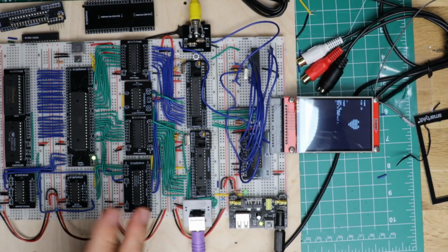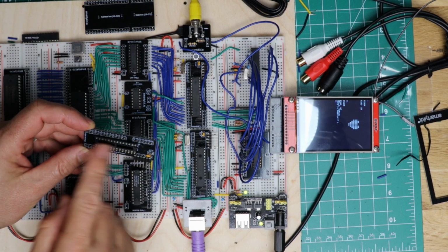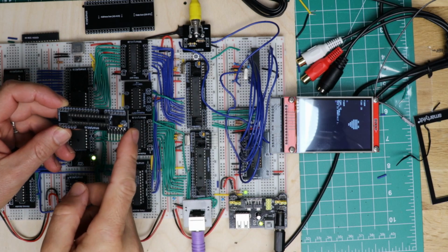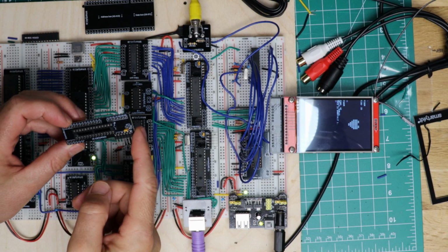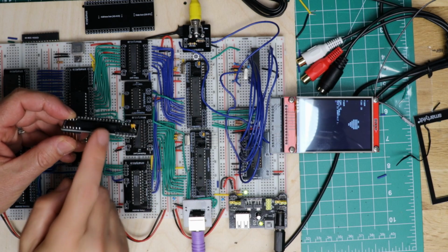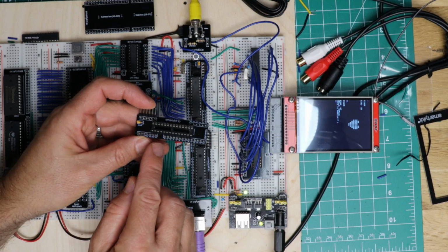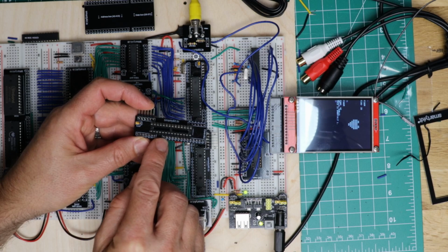Okay. So it turns out there were three problems. The biggest problem is that these Atmel boards, and these three boards are all exactly the same, are defective. SmartyKit is aware of this, and I've been told they're going to send a new one out. If you do a continuity test between D0, D1, and D2, you'll find that all those three are shorted out.